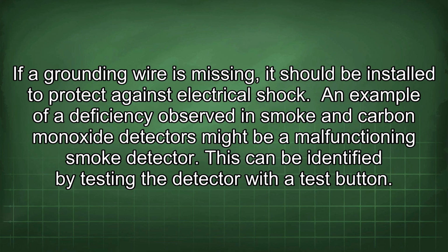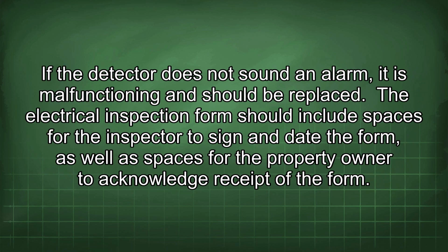An example of a deficiency observed in smoke and carbon monoxide detectors might be a malfunctioning smoke detector. This can be identified by testing the detector with a test button. If the detector does not sound an alarm, it is malfunctioning and should be replaced.